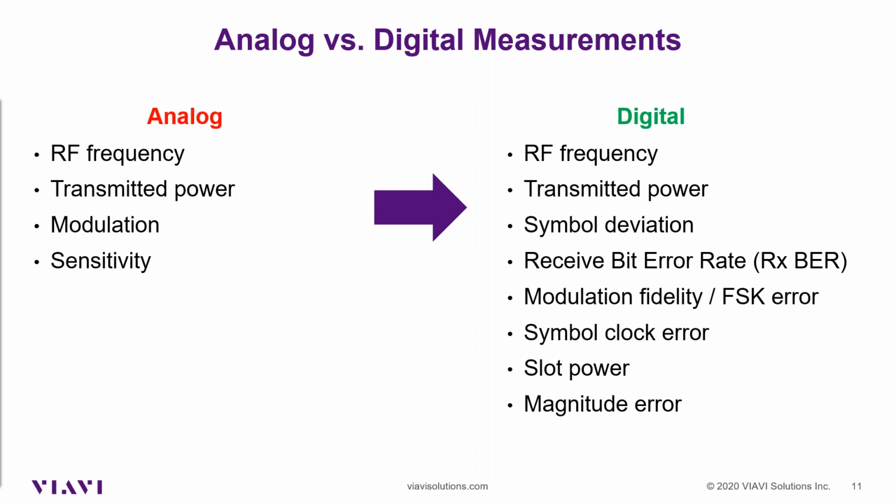So we went out and we did a bunch of troubleshooting on the base station, or the repeater rather. We swept the antenna, we swept the transmission line. We did all this work out there, couldn't find any problem there either. What could be the problem? And so at that point, we can take a closer look at that radio with the right test equipment, with a digital radio test set. We can look at that radio, and we can see that even though he did some maintenance on that radio, it's actually misaligned.